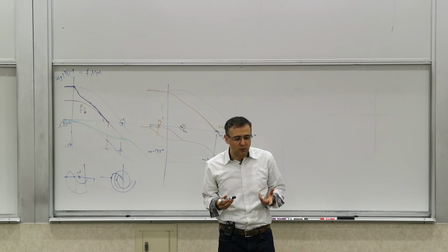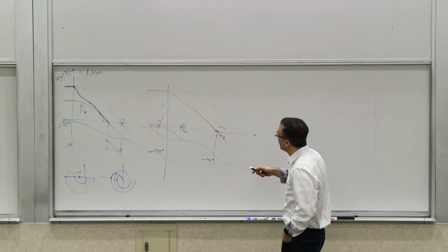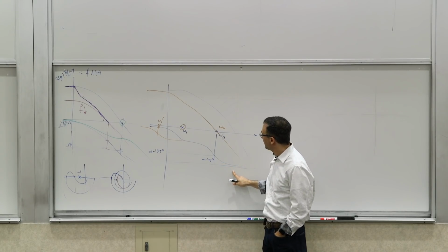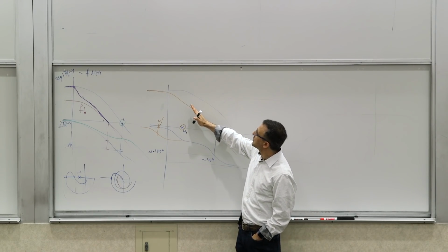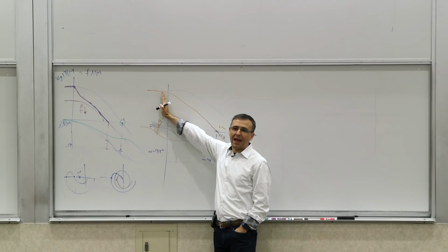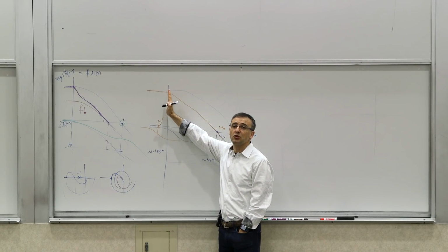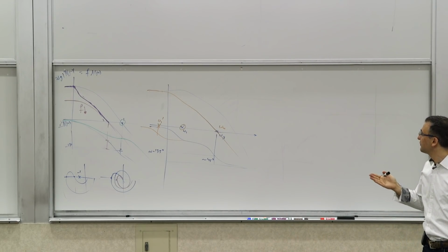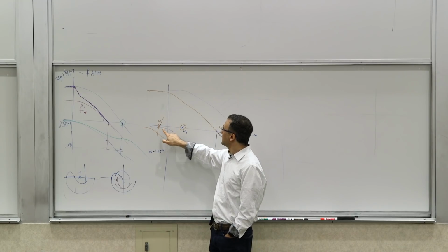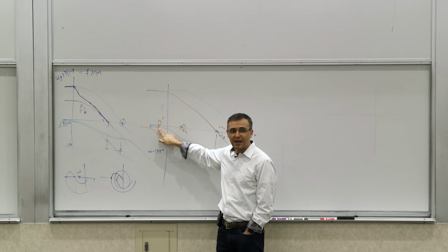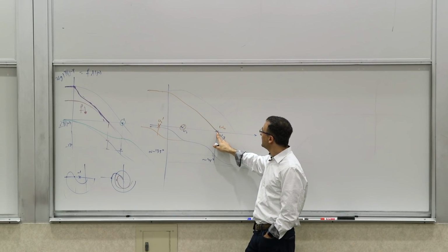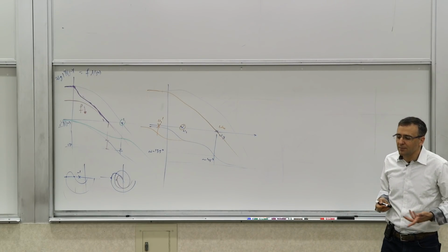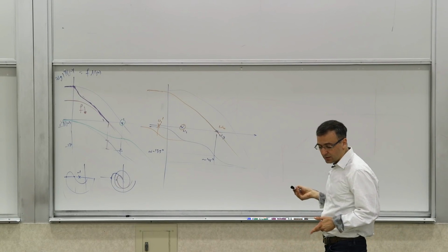From a circuit viewpoint, what we're trying to do is start with a system that looks like a blue curve, where you don't have sufficient phase margin, and you want to go to an orange one. One way to do this is to reduce the bandwidth, or basically make your dominant pole even more dominant, right? Reduce the frequency of your dominant pole even more in such a way that by the time you get to the unity frequency, you have sufficient phase, right? So this method of compensation is used a lot in circuit design.